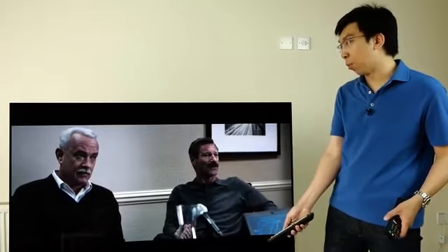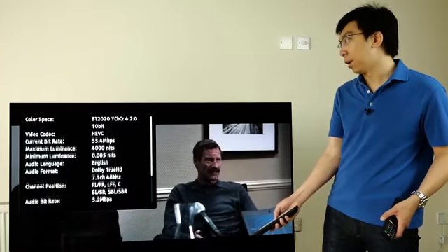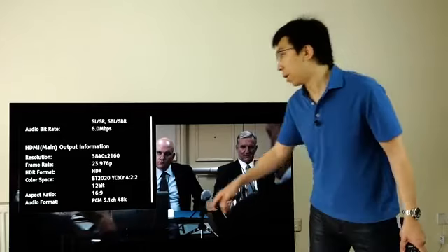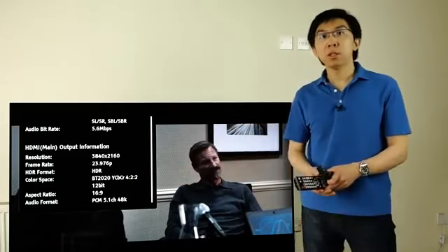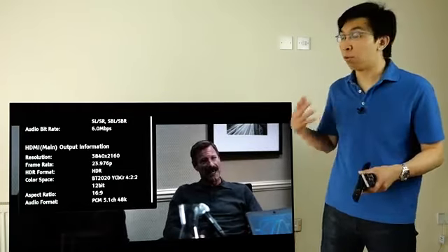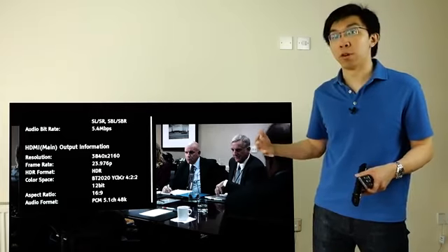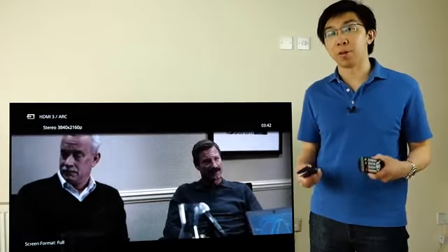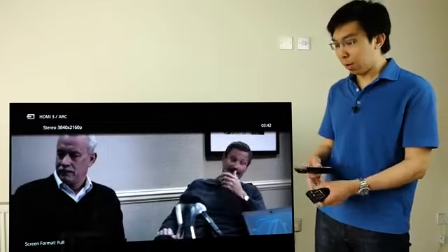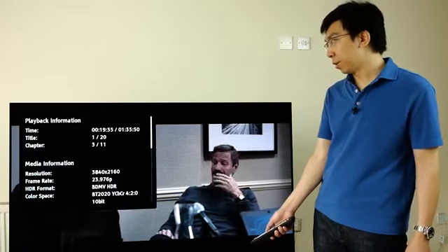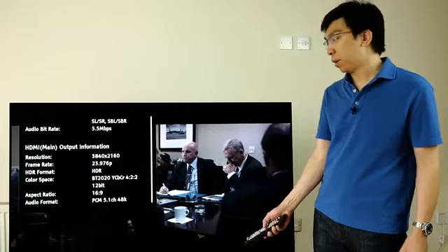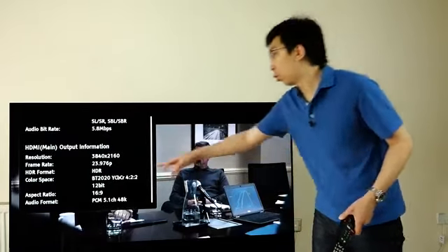But you can see from the information screen from the Oppo, if we long press the info button, that the chroma depth tops out at 12-bit 422. This is generally not a problem since Sony TVs usually do a very good job of converting 422 to 444 or RGB. Now let's take the HDMI cable and connect it to HDMI 3. With HDMI signal format left at its default setting of standard, we can see from Oppo's information screen that the chroma depth still tops out at 12-bit 422.